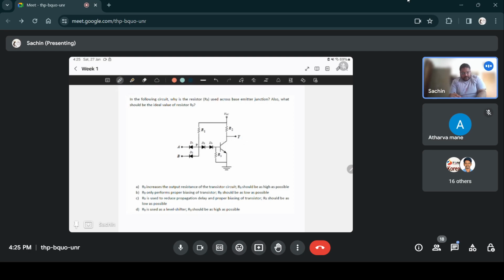when this transistor is on, this output is low, right? So it will be low, and when we want it to change to a high state, we'll give appropriate inputs and it will transition to a high state. But for it to go to a high state, this transistor should go from saturation to an off state, right? So for this transistor to switch off, this voltage VBE here should go below 0.7 volts.